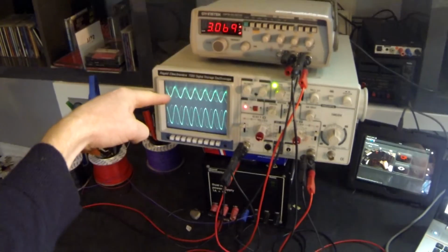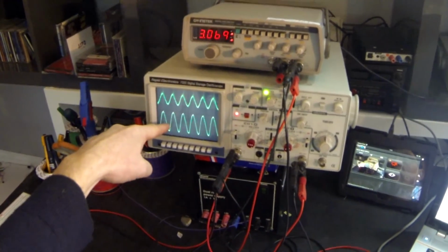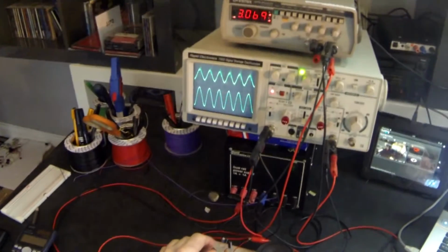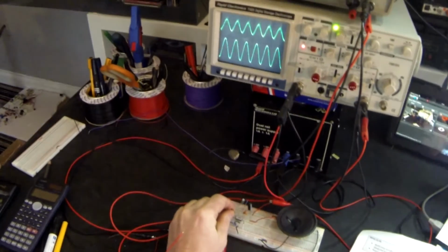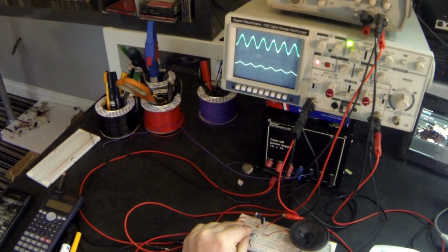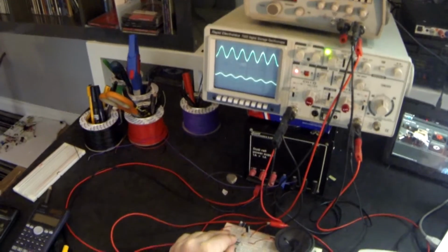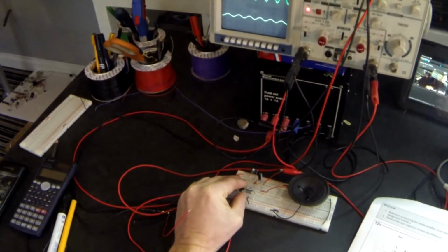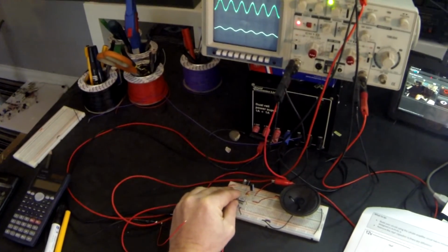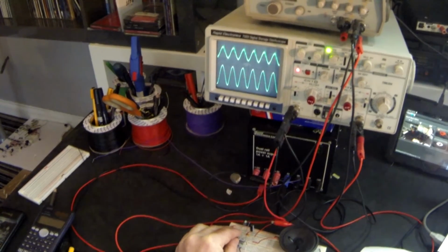At the moment, whilst it's shifting around, we can see that the input waveform and the output waveform have a gain of 200 because we still have our original settings. And as I pull out that 10 microfarad capacitor, have a listen and have a look. So you can see that the waveform became substantially smaller, and you can hear that the loudspeaker becomes substantially quieter. I'll put it back in. And pull it back out.